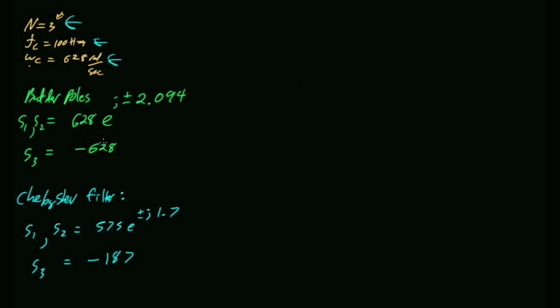All right? And that's the investigation that we started on Wednesday, right? So on Wednesday, I said, okay, what we're going to do is, first we're going to build a first-order filter, right? The first-order filter will give me my first-order pole. And then I'll daisy chain that onto a second-order filter, which will give me my 2 complex conjugate poles.